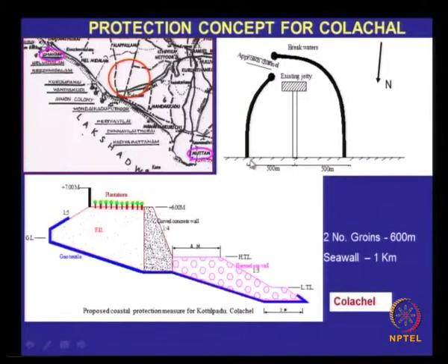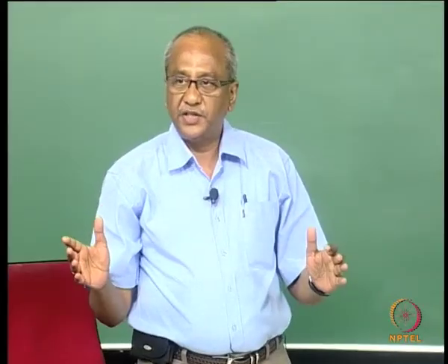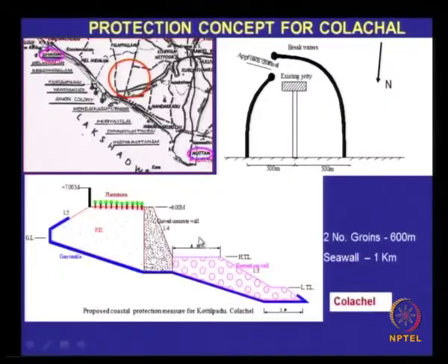So what was thought by us is that around 1 or 1.5 kilometers of the affected stretch needs to be constructed like this, having a seawall, but prior to that a pair of breakwaters. The alignment is not 100% fixed, it is only a concept, we need to do the detailed engineering.